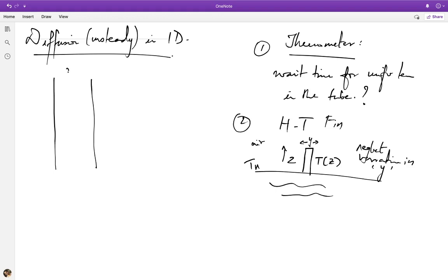And this is, let's say, for us now the x direction across the slab, and we neglect variations along the slab or transfers to the slab because we say the temperature there is uniform, not because of conduction, but because the boundary conditions are such that the temperature diffuses uniformly, and there's only variations in the x direction. So now on one wall, which corresponds to x equal to 0, we say the concentration is equal to C naught. Instead of temperature, let's work with concentration, because later I would want to introduce a reaction.